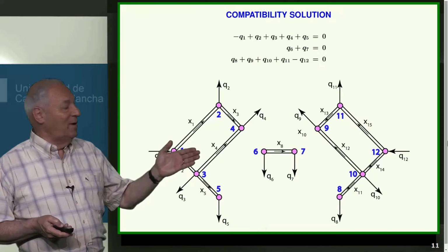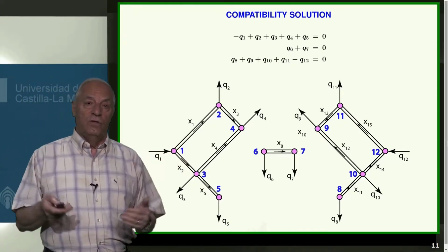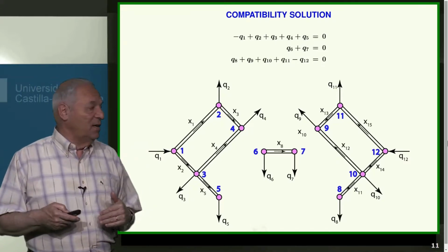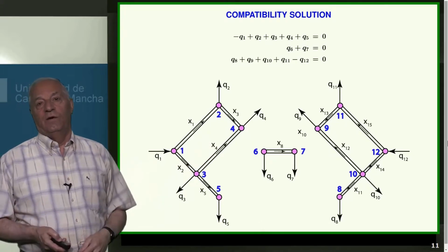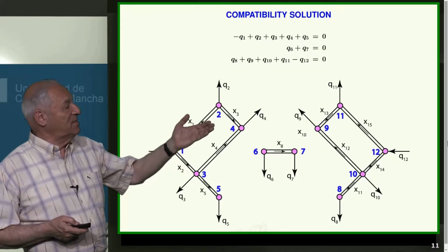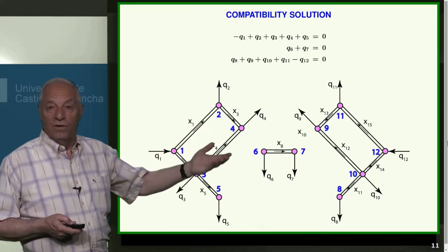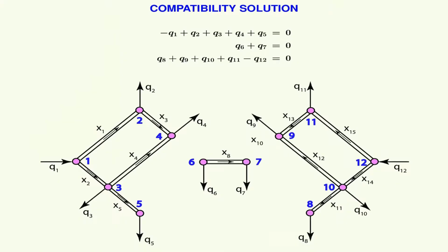If in some case we cut the network, for example, if we remove 4 pipes, as you have there in the graph, what is going to occur is that as compatibility condition, instead of a single equation, we will get 3, which correspond to the fact that what comes in and what comes out, in each of the 3 parts, has to be equal to 0. This is interesting, because there is a correspondence between the mathematical conditions, which are the 3 above, and the 3 physical conditions, which are the ones that we must get.